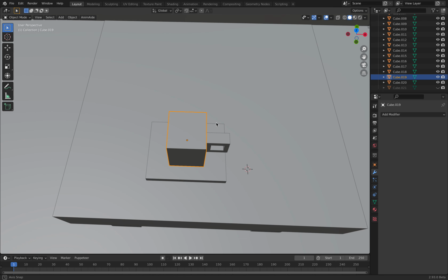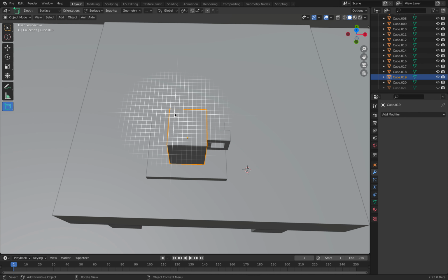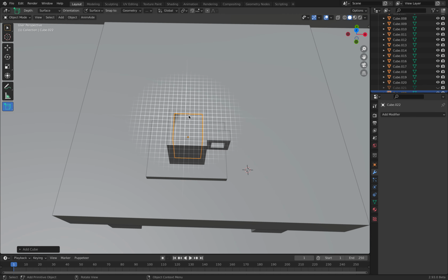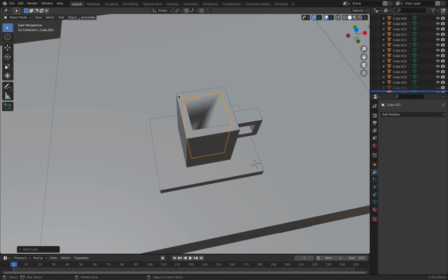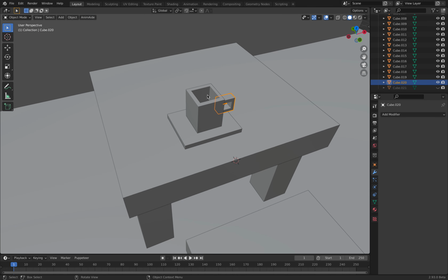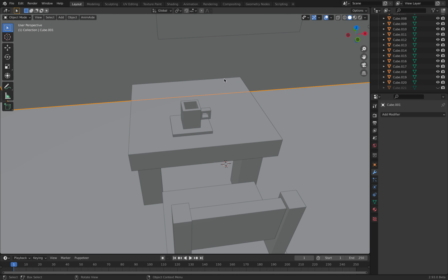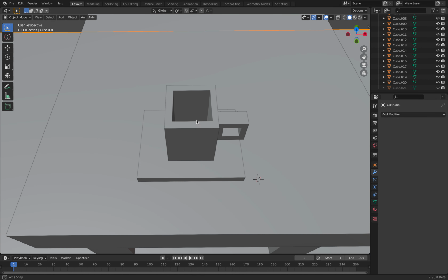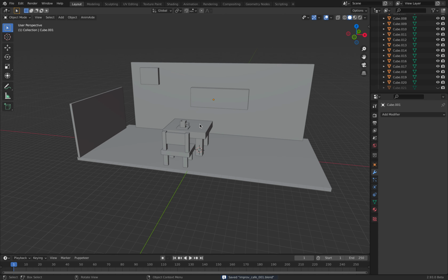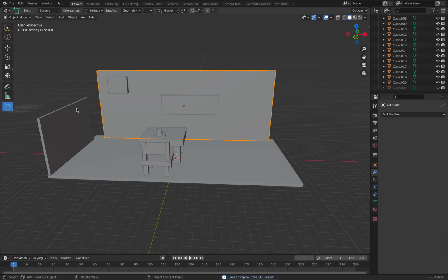So for example, if we want to draw this cup, if we want to kind of cut in, so I already drew that object. I want to cut into this guy. All I need to do is Control-Shift-B and just difference. So it's going to cut through the objects. We don't have a modifier, it's just going to do it for us. Again, it's not perfectly centered, but it's okay because we're just making a simple basic thing, just for fun.